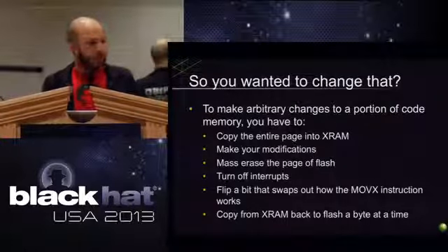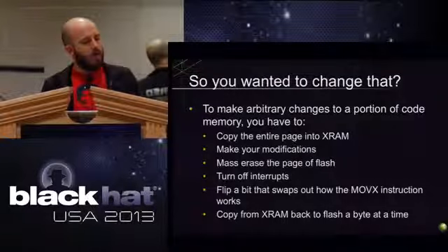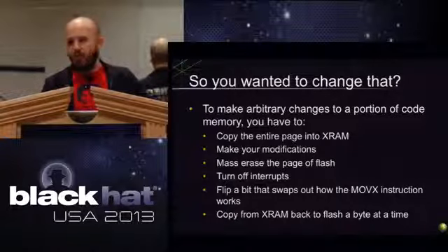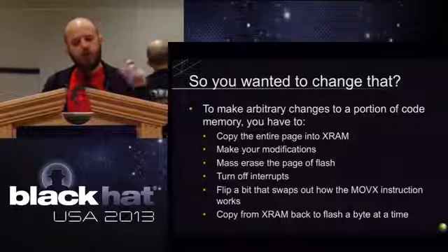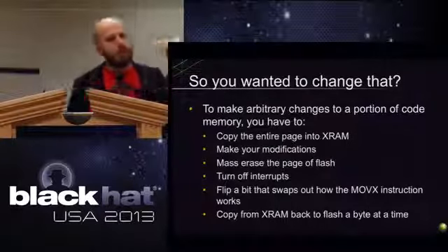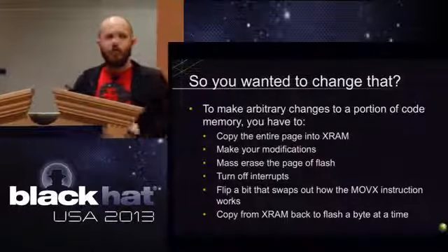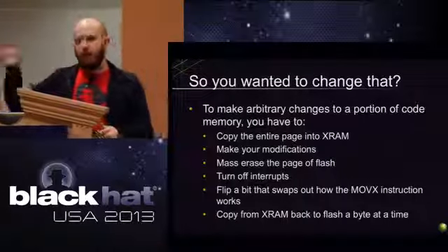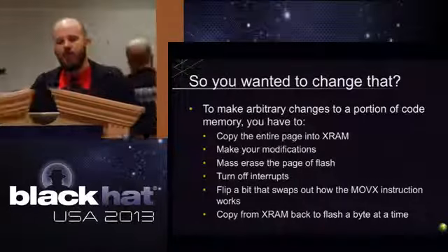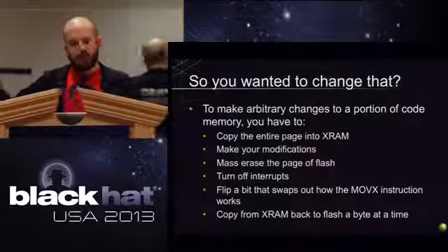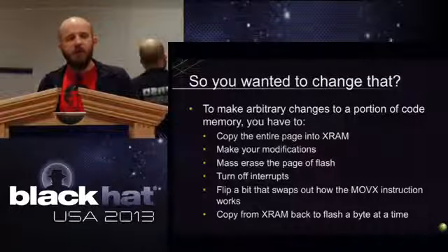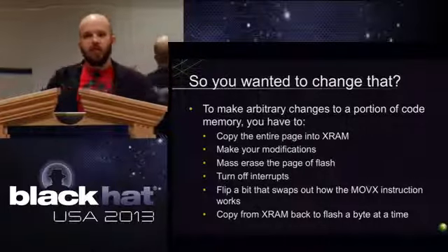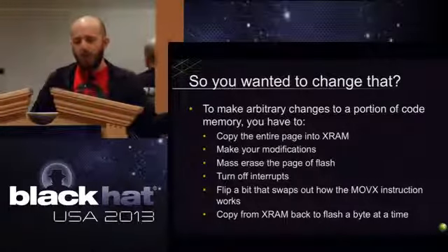The way this particular Harvard implementation works, like I mentioned, normally you can never modify the code page, you can never modify Flash. The way it works is that there's this movx instruction, where normally it means copy data to or from XDATA. XDATA being a very particular section of memory, where all the data is stored, like all your variables and all that kind of stuff, not code. And you flip a certain bit, and suddenly that same instruction now makes a modification to the Flash memory.